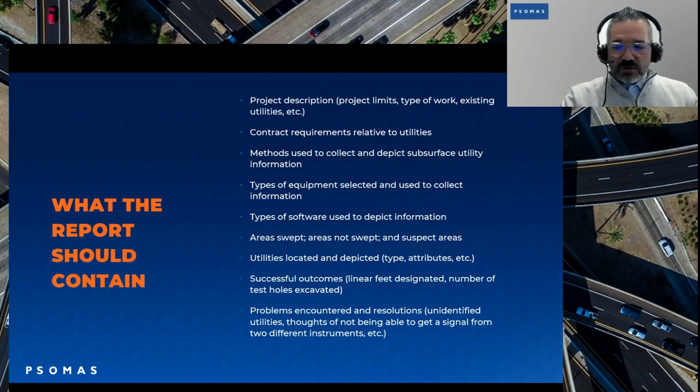Problems encountered and resolutions, unidentified utilities, thoughts of not being able to get signal from two different instruments. This gives the opportunity for that detection crew to be able to say, hey, here's what we saw, here's what we think, and then giving more information to the professional engineer so that they can assign the risk.